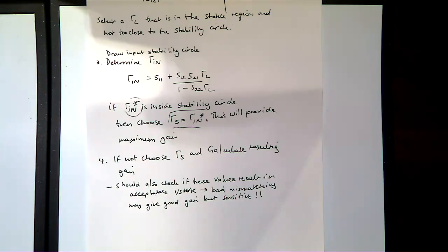Right. Likewise, what it's saying is if you've got an amplifier and you've got to build a particular matching network to it, the minimum voltage and the maximum voltage at the input varies from these two values, right? So therefore, the closer to 1 it is, the smaller the maximum to minimum voltage. The larger it is, the larger the difference, right?